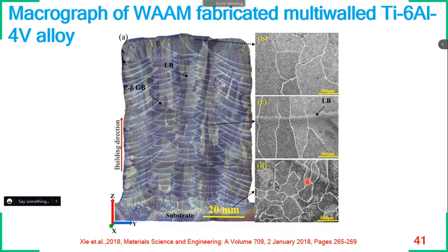Heat dissipation takes place from top to bottom, so the bottommost layer can quickly dissipate the heat, but once the substrate itself gets overheated, no further heat dissipation is possible. So the overheated substrate and the bottommost layer have a lot of heat stagnation, which results in the evolution of stress-free grains, which we call recrystallized grains. That is how the bottommost layer was featured with fine grains, whereas the top and middle layers were featured with coarser columnar grains.